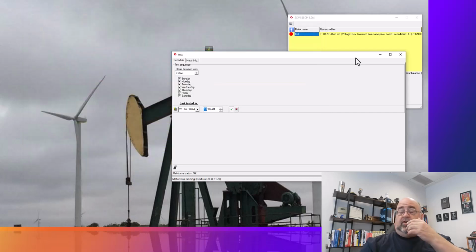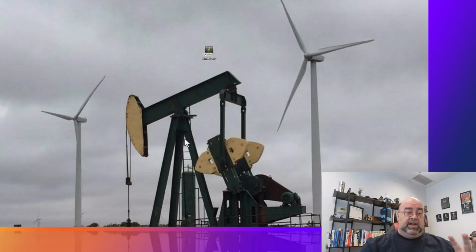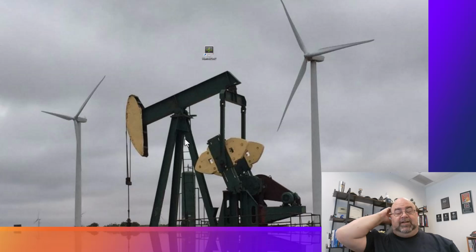And that's about it. So also what's happened the past week, and we talked about acoustic imaging before. Well, next week I'm going to get into RCFA stuff, but the acoustic imaging experience last week, we went out to a site and we were looking at stuff, and I just pointed at a fan that's not electrically operated, and it gave me data. It told me that I had corona, which it just was a raised noise floor from turbulence from the fan.